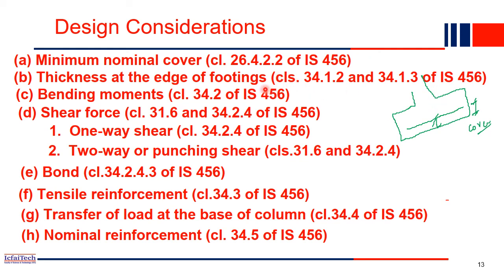So for the calculation of bending moment, you will get it in this clause number 34.2, where you can directly use the different bending moments from the clause itself. Then to compute the shear force, you will have clause number 31.6 and clause number 34.2.4. You will get the shear force there.